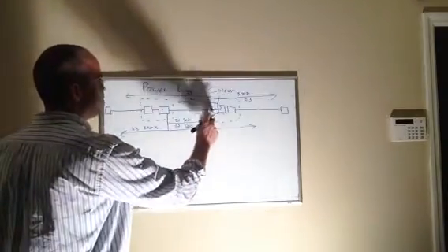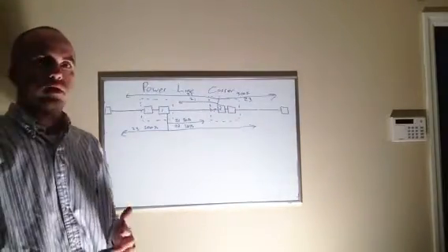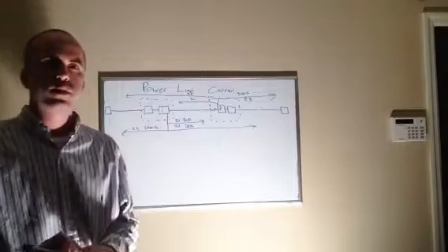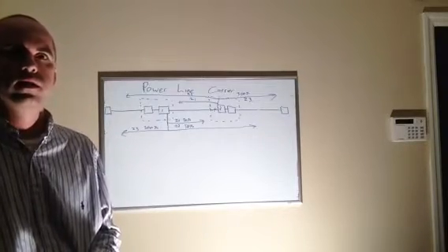So that's how pilot protection gives us, the primary purpose is to give us high speed tripping on 100% of the line. You need to remember that.